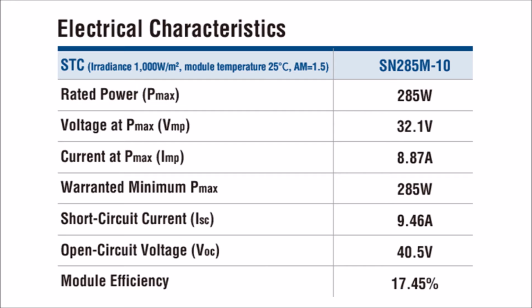The maximum amperage is the short circuit current, and the open circuit voltage is the maximum voltage, how high the voltage would be if it were fully energized without being under any load at all, like a light switch turned off with electrical power on one side of the switch and just metal connected to the ground on the other with nothing but voltage potential in between.